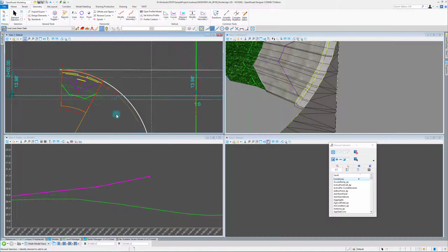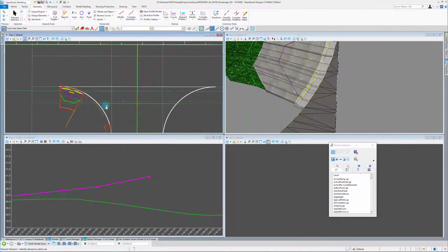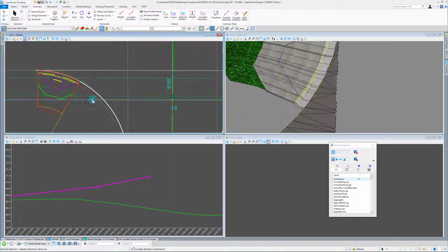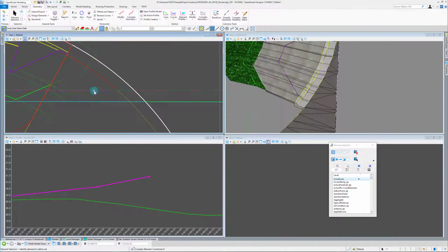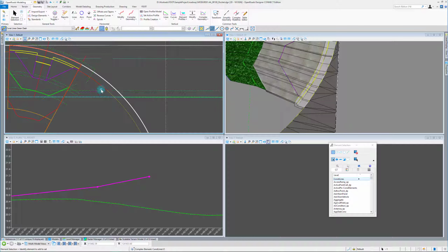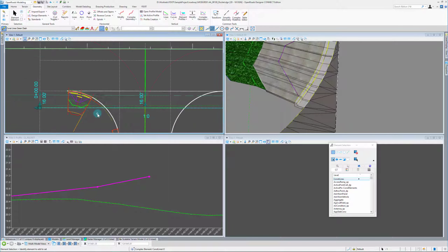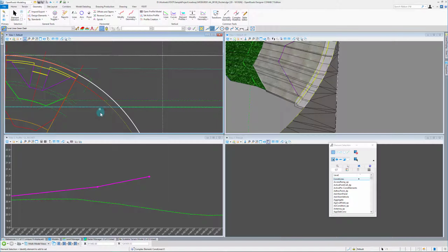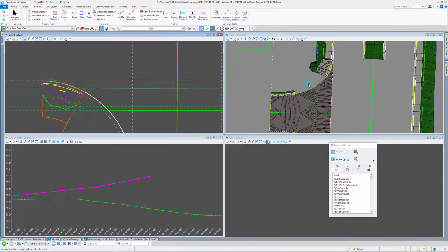Now that's ruled there. What we're going to do with this one is, I know this is basically the back of my sidewalk, so I need to have that extend across here, but this ramp width, according to the DOT standards for a CRD, is 5 feet this way. So instead of ruling this to that line, I'm going to change the rule to this line. Now it's going to screw up what we're doing over here for a second, which is okay.